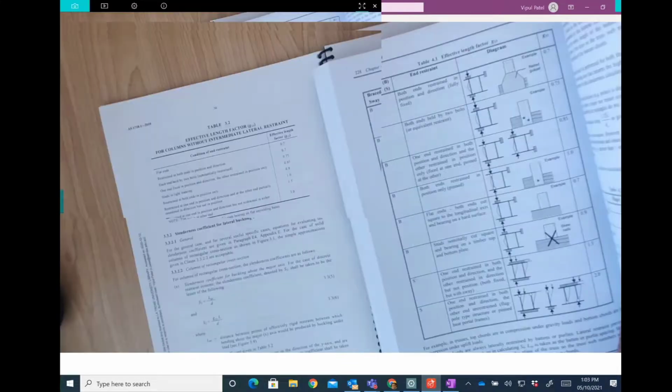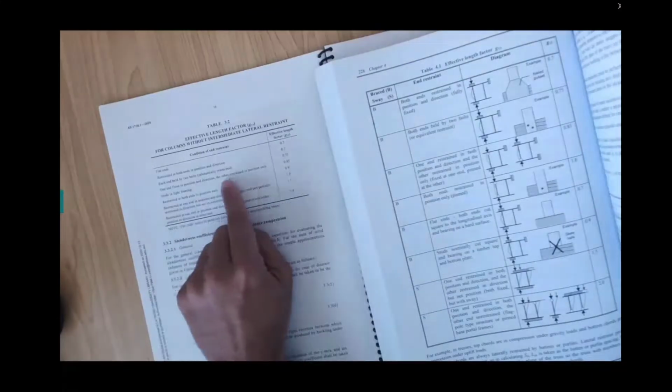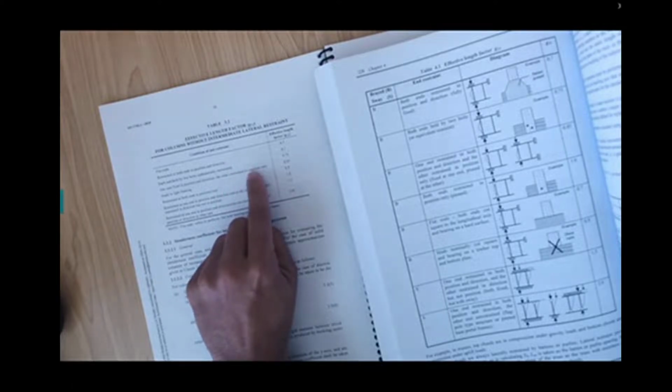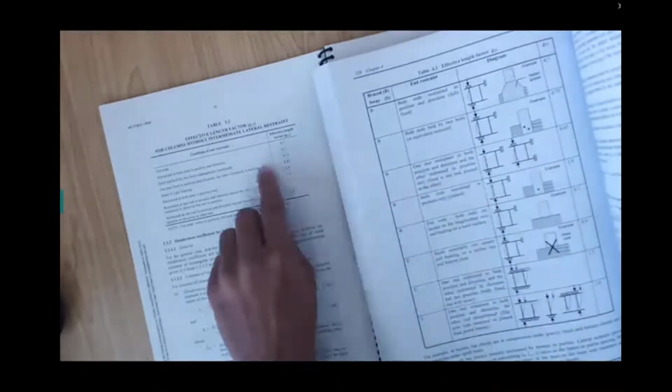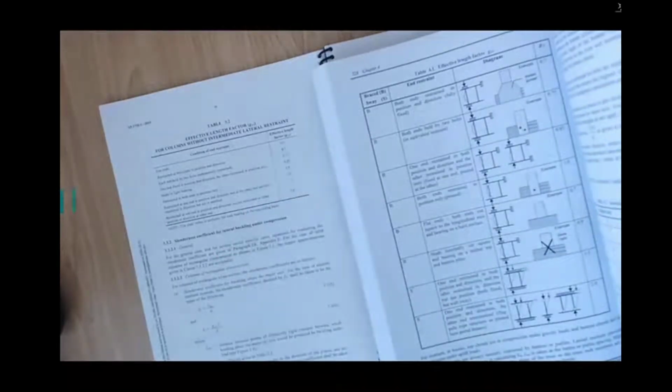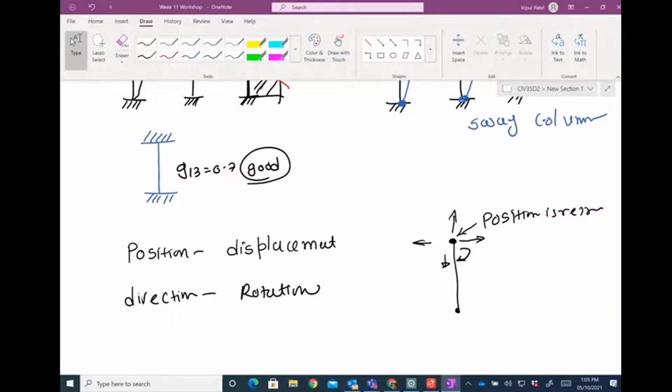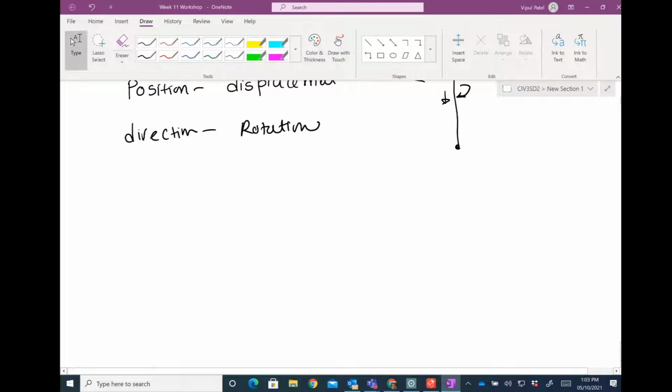So in that vocabulary it says that the other restraint is only position. So direction is not restrained. So you have a pin. By the way, this case is a fix and pin, 0.85. So for 0.7 and 0.75 we get a partial, little bit of rotation not allowed, that is 0.75 when you have two bolts. Another one is the pin. Let me put that pin like this, and you have fix.